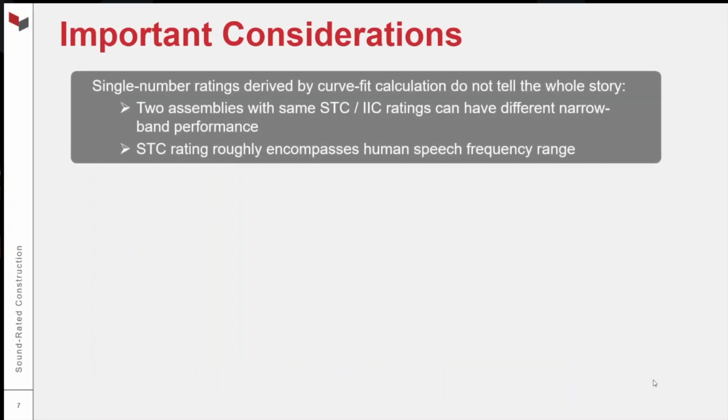So, some important considerations when it comes to STC and IIC. The first, as I mentioned, is that these are single number ratings. When we do the testing in the lab or in the field, the field tests for both airborne and impact are very similar. You're just doing it under field conditions, with slightly different ASTM standards. I'll reference them later when we look at the IBC.